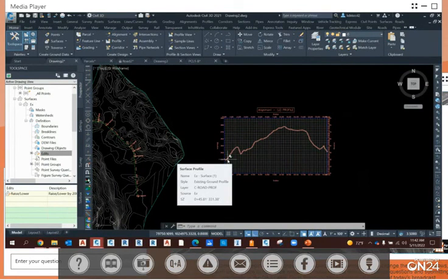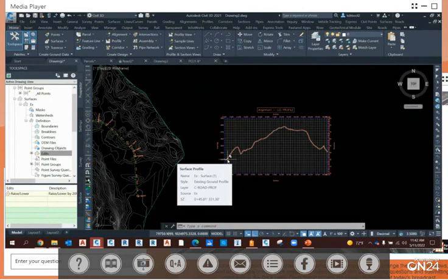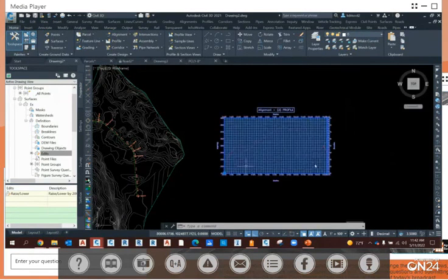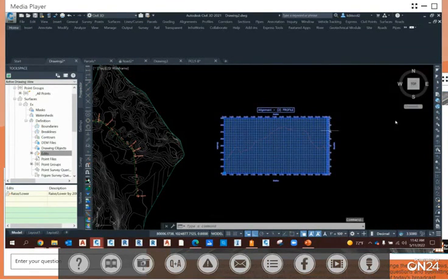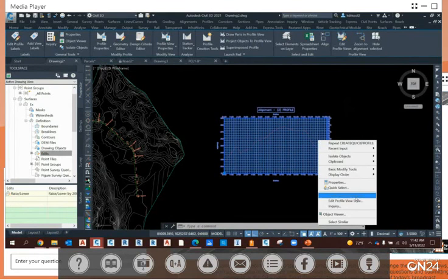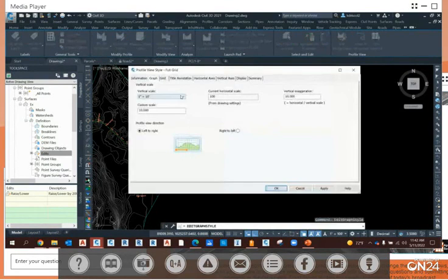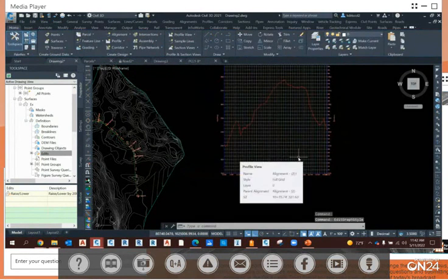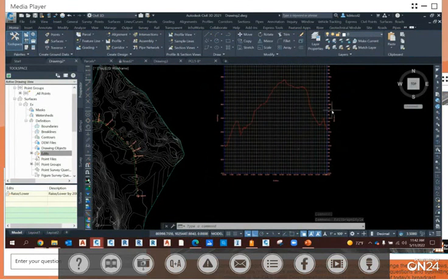And that's why these design workflows show productivity gains from AutoCAD that ultimately in Civil 3D takes seconds. And if I need to exaggerate what this scale is for my profile view, I'll just pick on it, edit profile view, and I'll change the exaggeration scale. There's my change. In AutoCAD, now we have to redo all that over.